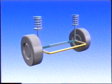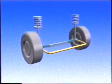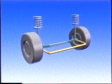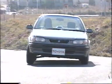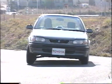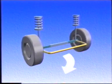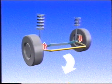When the left and right wheels move up and down the same amount in the same direction, torsion is not applied to the stabilizer, and resistance is not generated. But during cornering, the inside wheels will lose contact with the road surface, and the outside wheels will be pressed down. This causes the stabilizer to be twisted. The spring resistance generated reduces the leaning of the vehicle and keeps the body level.